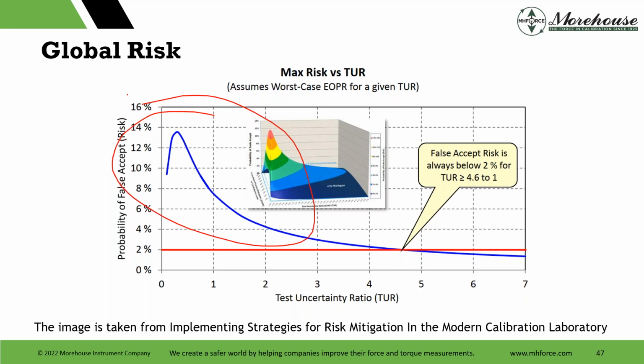The problem of falsely accepting products drops off significantly, because nearly everything is falsely rejected. I mean, you don't have your TURs under any control, and you really don't know what's going on. Your measurements are all over the place, and therefore, when it gets super, super low in this region after it meets the peak, you don't know what you're doing, basically.